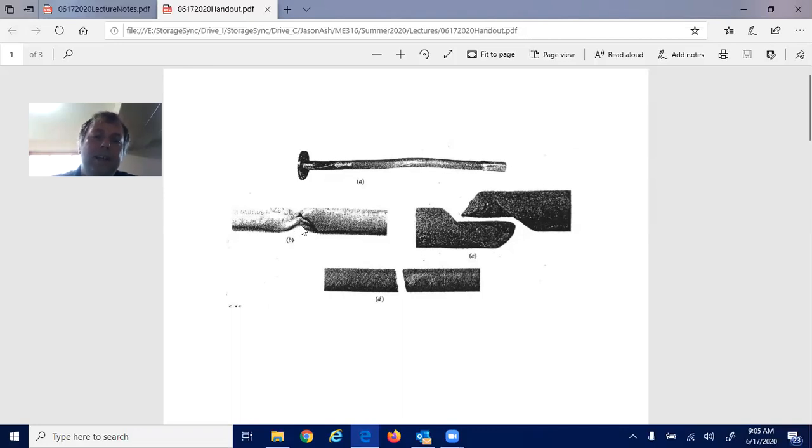And it's kind of interesting. You'll find that the majority of the shear stress is absorbed by the outer portion of the material of the cross section. I think it's something like about 94% of the torque is carried by the outer half of, say, a solid rod.